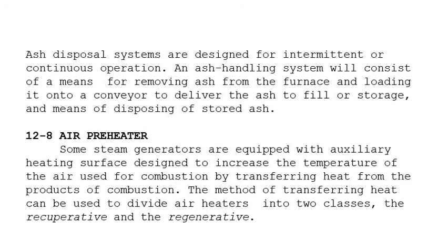So, the air preheater. Some steam generators are equipped with auxiliary heating circuits designed to increase the temperature of the air for combustion by transferring heat from the products of combustion. The method of transferring heat can be used to divide air heaters into two classes: the recuperative and the regenerative. So those are the two types of air preheater.